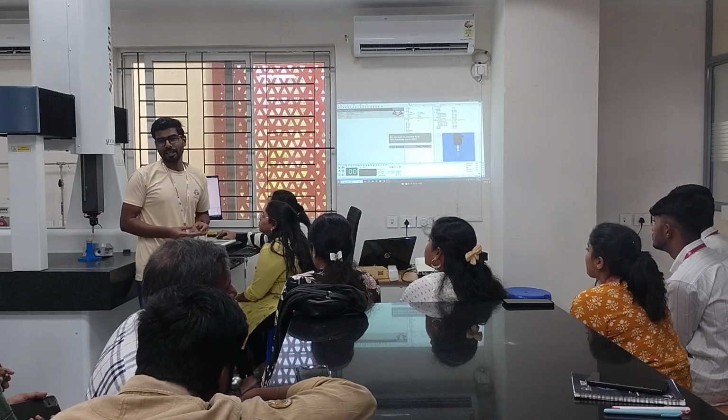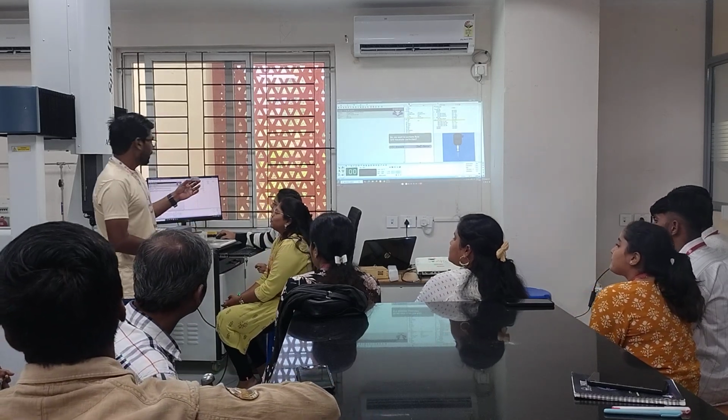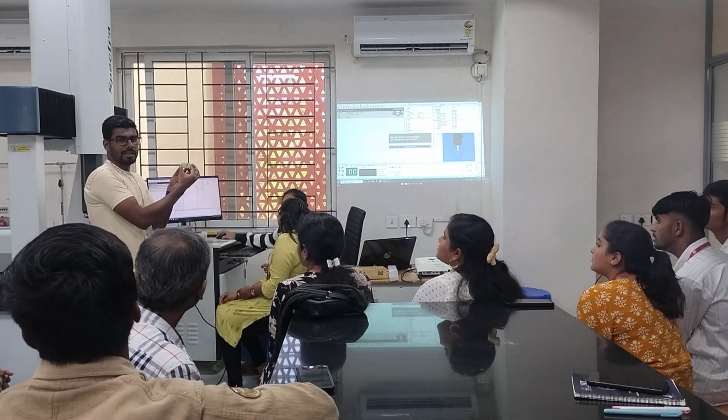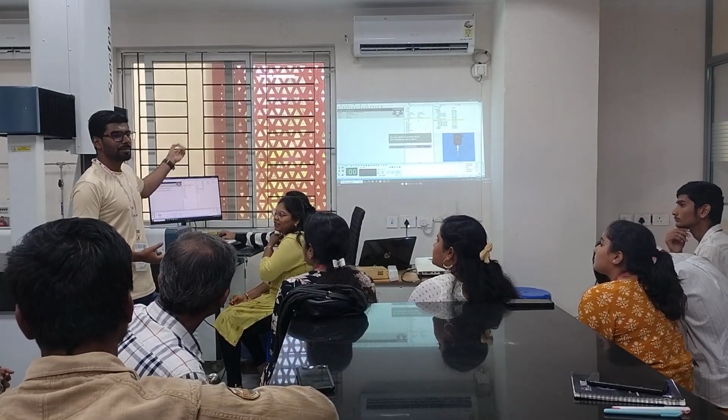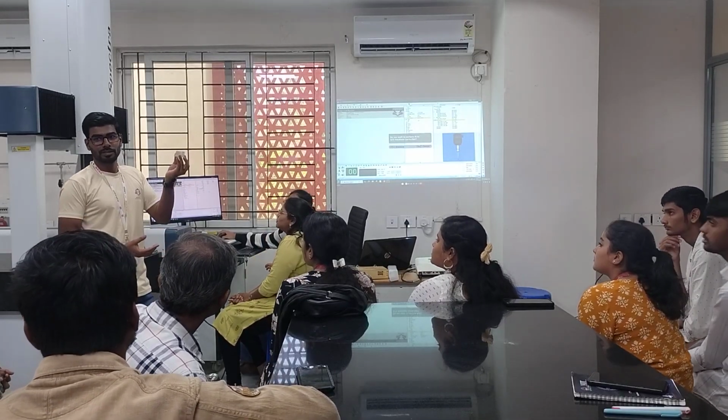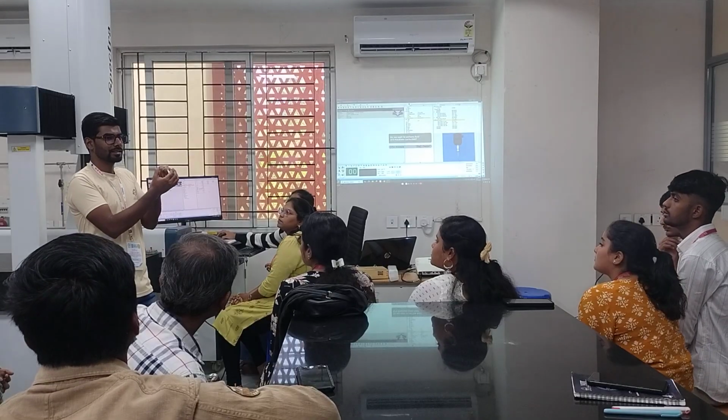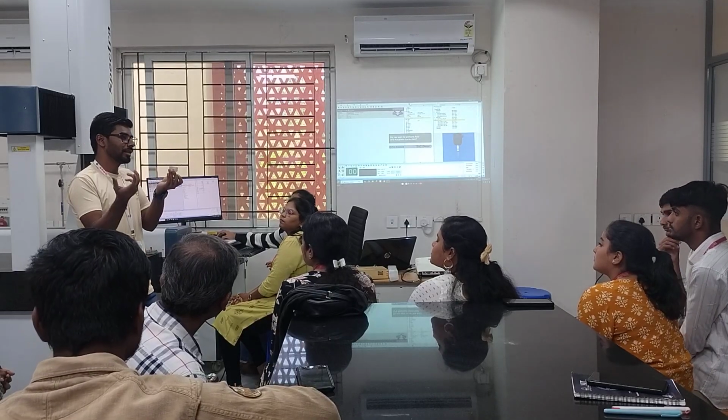So we are going to see that this dimension given is 40. It is printed on DLP. But what is missing? It is coming as 39. Why is it so? It is less compared to the given design which I have made.